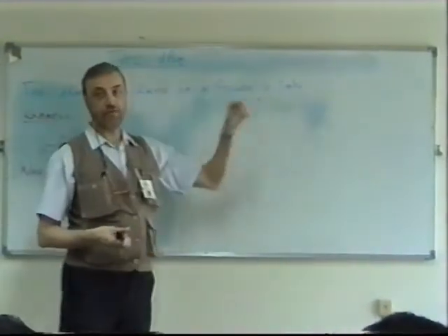Now, this dBm is a measure of power. What's dB a measure of? It's a ratio, yes, that's right. Now, there's a big difference between dB and dBm. dB is a ratio of powers. It doesn't have any units, apart from dB. You don't talk about watts or milliwatts or anything like that. It's a ratio of two powers. And dBm is the ratio of power, but it's fixed to 1 milliwatt. So it's a reference.